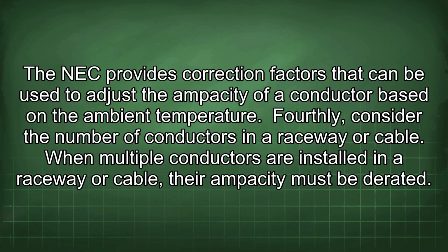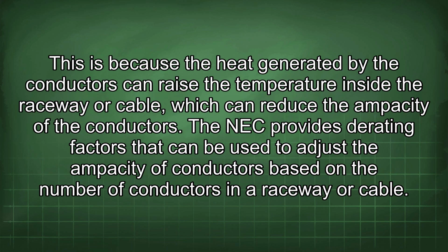Fourthly, consider the number of conductors in a raceway or cable. When multiple conductors are installed in a raceway or cable, their ampacity must be derated. This is because the heat generated by the conductors can raise the temperature inside the raceway or cable, which can reduce the ampacity of the conductors. The NEC provides derating factors that can be used to adjust the ampacity of conductors based on the number of conductors in a raceway or cable.